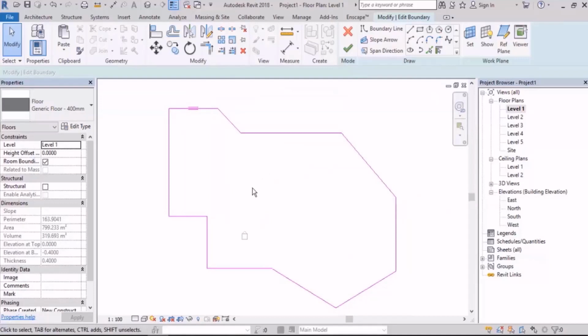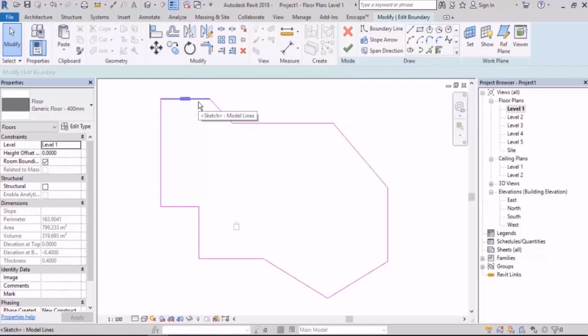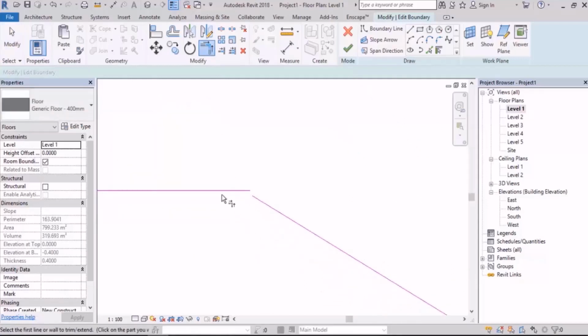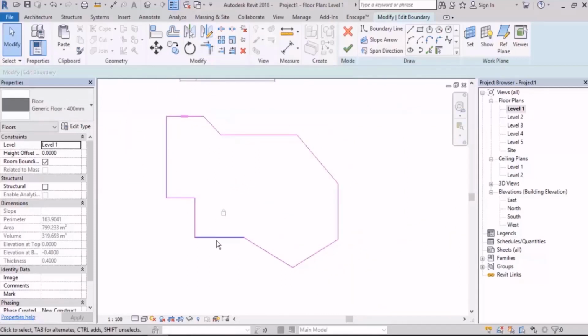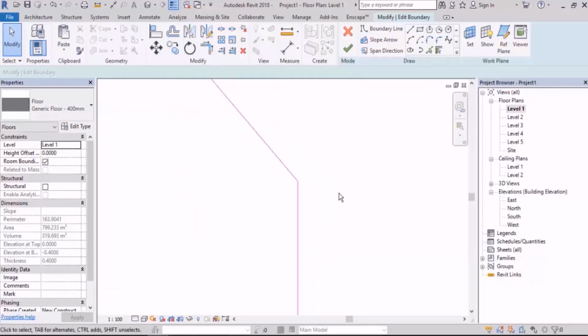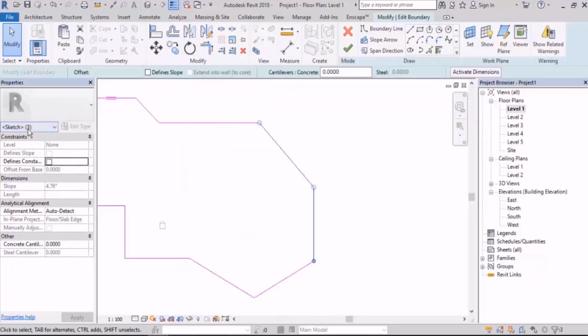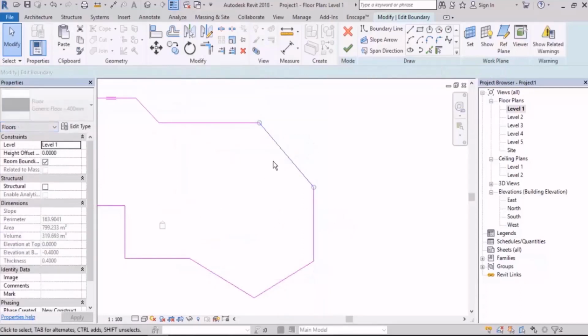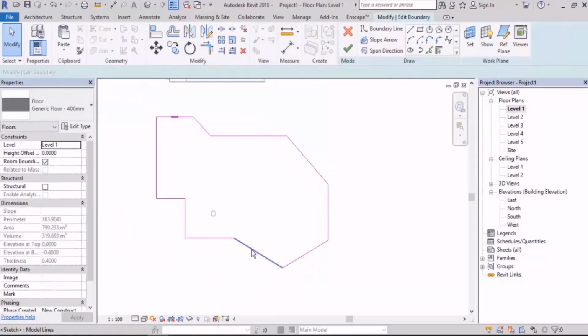But there's also another way, which is a golden way to do it. So move your mouse on one of these lines and tap once. You see, it's stuck, and that means that you have an issue here that you should know. So when I zoom in, I see that yes, it's open. So I trim it. Again, I move my mouse somewhere, no matter where, and then tap, and I see that it doesn't stick, so it's okay. But here, what is the problem? It's not open, definitely. So when I have doubt, I open a box. It's not this one, but it's this one. So I select it and delete it. Again, tap. It goes until the end, so it seems to be okay.